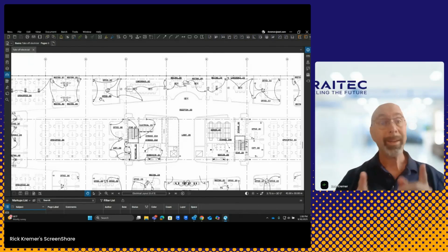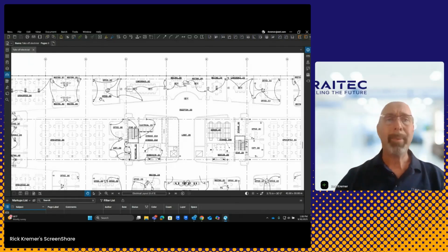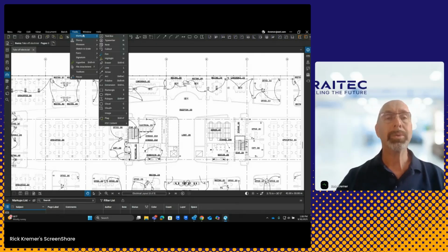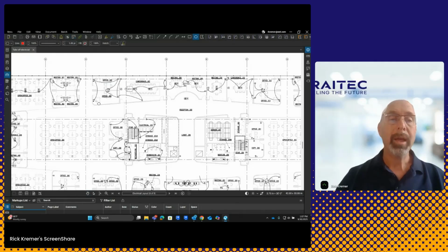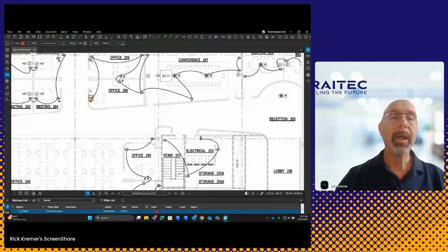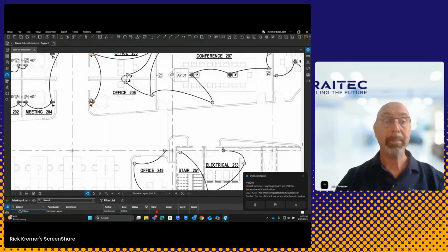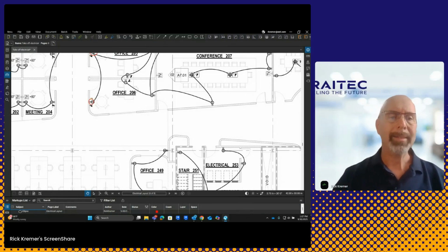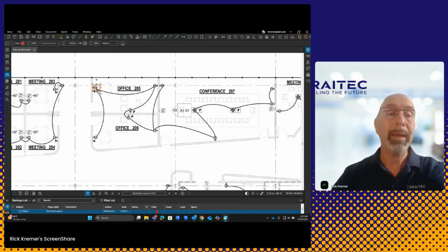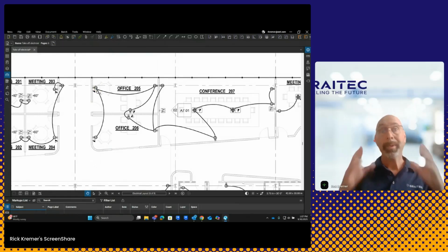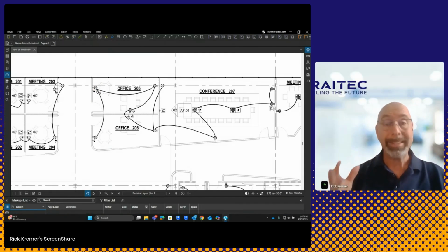Now, some of you that I've talked to on the phone before might do this in a unique way. You might go over to Tools, Markup over here, and just draw, for example, a circle and say, okay, there's one here, and then I'm going to go back again and keep drawing it, and here's another one, and I'm going to manually go through and place these. Well, that's really no different than hitting it with a highlighter. Let me go ahead and delete these real quick, and I'm going to show you a methodology that we can do using Bluebeam Review's built-in search feature.